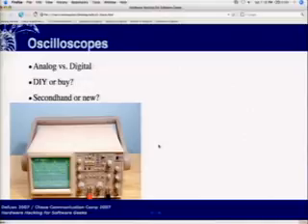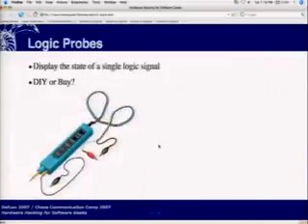Well, another alternative is to use USB-based oscilloscopes, but the display is not going to be anywhere near real-time, and there's usually going to be a noticeable 3-4 second delay. Like if you're monitoring a serial port with it and you hit a button on your console and watch it go on the oscilloscope, it might be 3 seconds before you actually see it. But those USB instruments can be very useful because it'll only be a couple $100 rather than tens of thousands of dollars for the equivalent full instrument that you'd see in a lab.